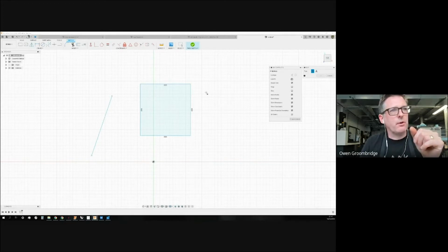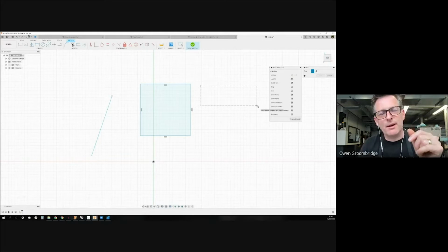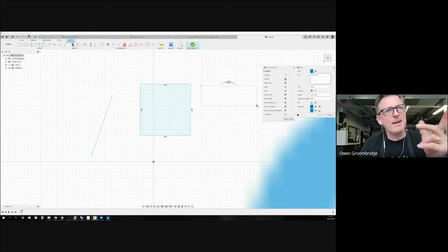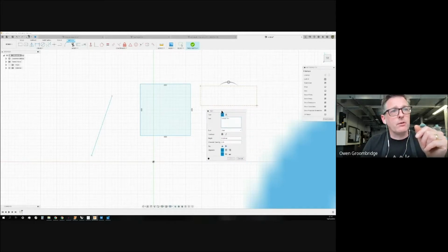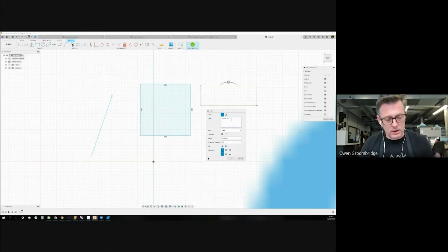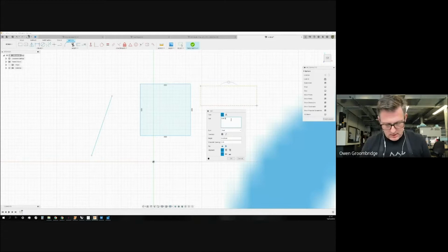And I've got a crosshairs with a little A on it. And if I left click, drag one corner, and then left click another corner, I can even rotate that text box if I wanted to. And in the dialog box that I've just dragged under it, I can put in a sample text. Okay, so SLA PM E1 S4. Right.